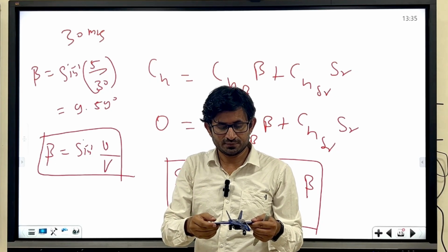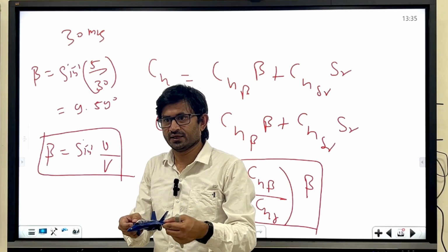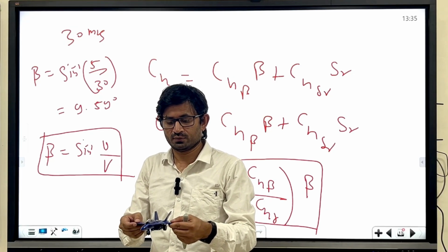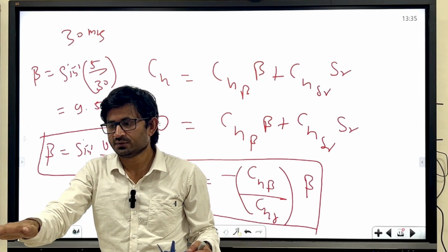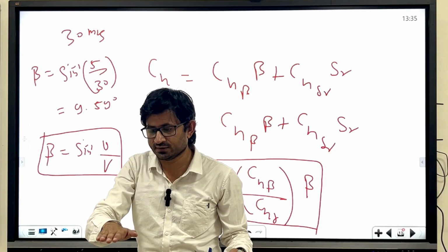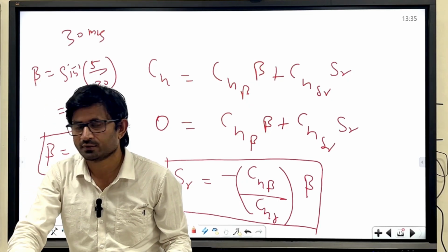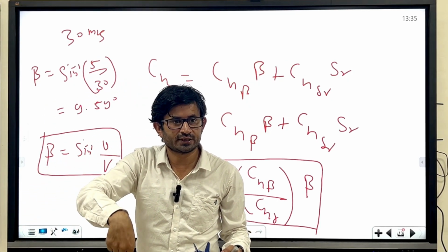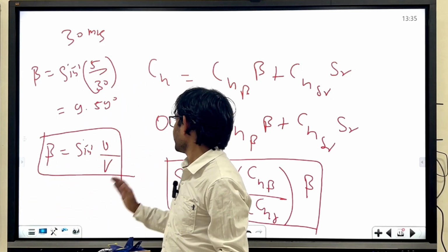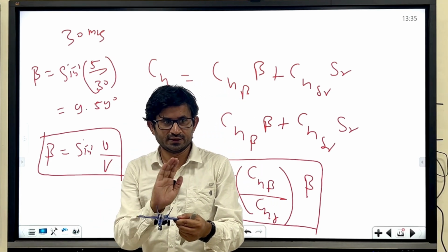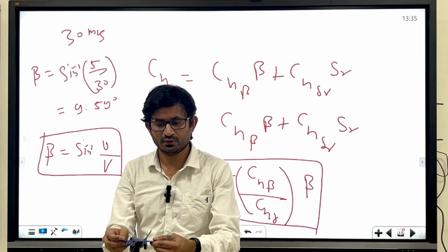Okay. So that means the aircraft will try to take a yaw. It will try to have a side slip like this. If you have a side slip like this and you are landing, then you will not touch down at the landing center point. You will skid, right? But if you deflect the rudder in this direction, at 10 degrees, you will counter the yaw and you can land your aircraft.